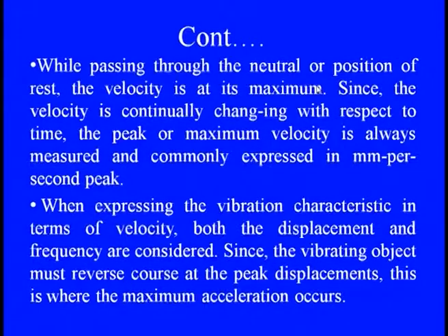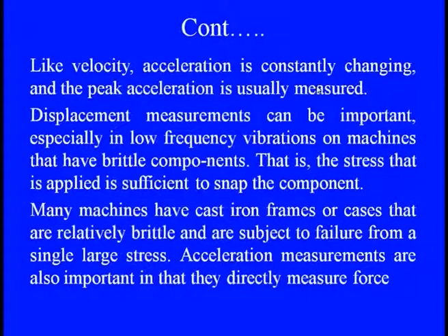And since the vibrating object must reverse its course of action at the peak displacement, this is always where the maximum accelerations occur. So we need to consider the displacement, meaning the maximum amplitude, and the frequency for the measurement of velocity. Like velocity, acceleration is also continuously changing, and the peak acceleration is usually measured.